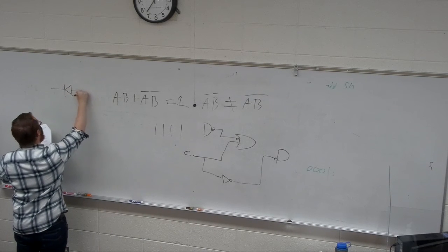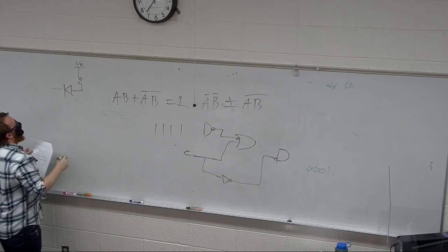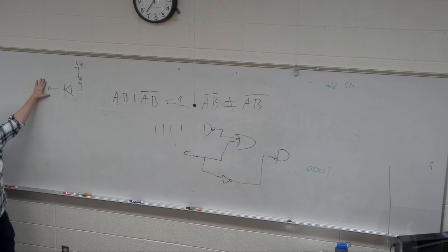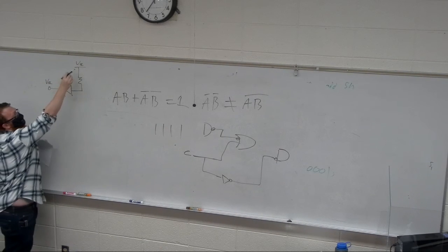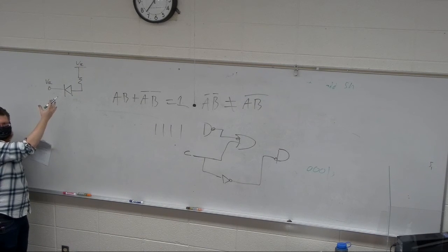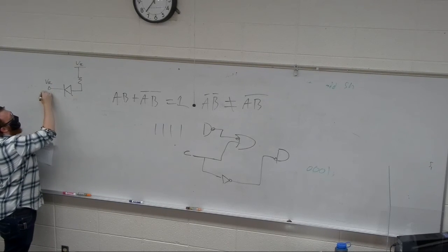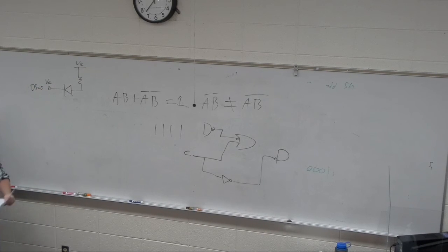I would say more than half of you got this right. And those that missed it at least got the right idea, right? I'm just asking, when does this LED turn on? If this is VCC over here, then I go from 5 volts to 5 volts and nothing happens, right? So the circuit doesn't do anything unless there's a difference in voltage. So when the signal in is equal to 0, then current can flow. If it's high, no current flows.